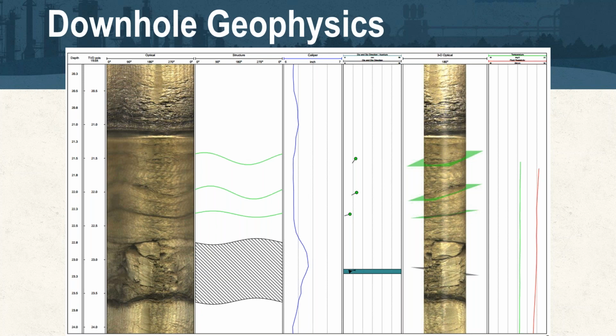Yes, you could use pretty much any size you want. And what we always advise, or what we stress when we do coring versus setting the characterization points, is that the core location is independent from the other characterization points. What we found from experience is that if you do a core location and then try to over drill or ream that core location out, even the best efforts of a very skilled drilling contractor can have some level of deflection from that original path.